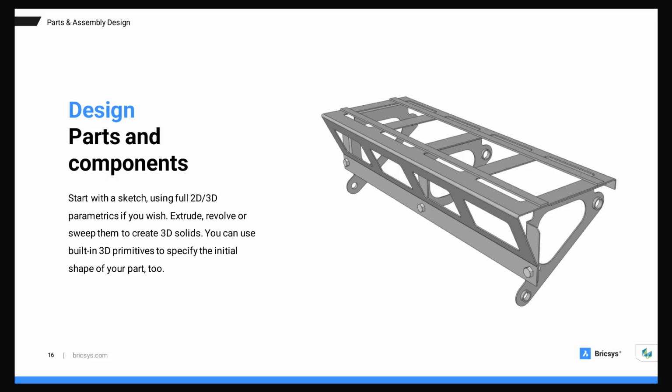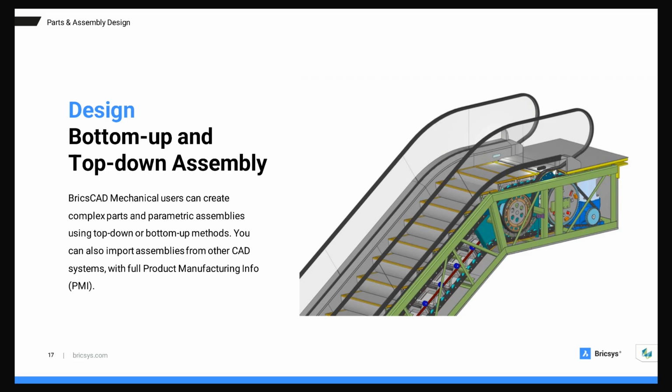Create a sheet metal component. You can run scripts. You can have a template set up. Boom. There's your drafting, your detailed 2D drawing of a flat pattern, a blank size to send to a plasma cutter, for example, with a bend table, your bend allowances, your K-factor, all taken care of. It's all sorted in the background. Really great stuff. Because of time, we're only scratching the surface of BricsCAD Mechanical.